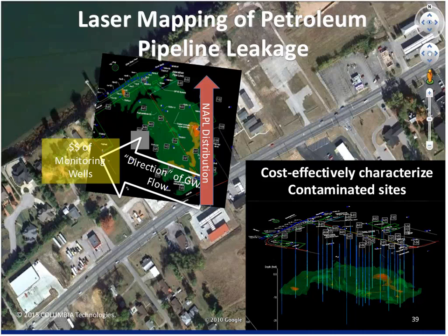There's another example of the competition. Here's an example where we've got a pipeline corridor here. Pipeline rupture occurs at this location. The conceptual site model of local or regional groundwater direction is believed to be in the white arrow direction. We have our water body over here. Our concern is the pipeline rupture is going to move towards the water body in that direction. Immediate reaction was to install a series of groundwater monitoring wells in the neighborhood, screen them with conventional information, and basically came up with ambiguous or non-existent data regarding the LNAPL.